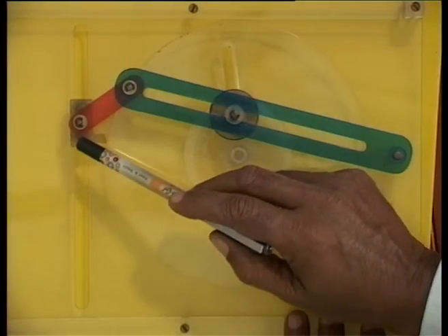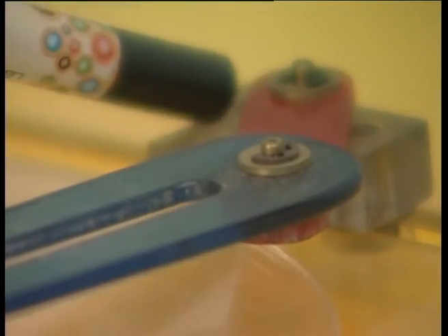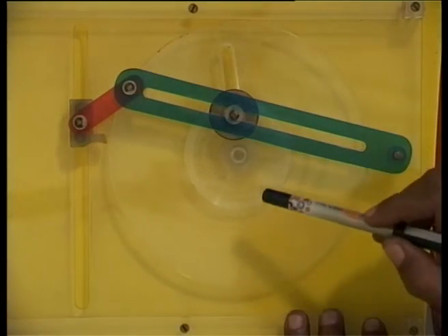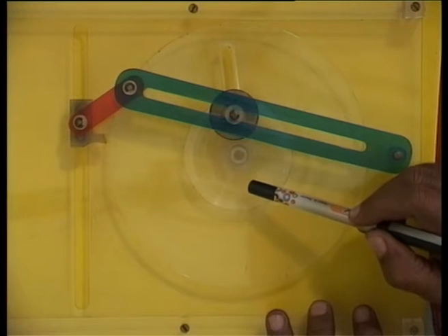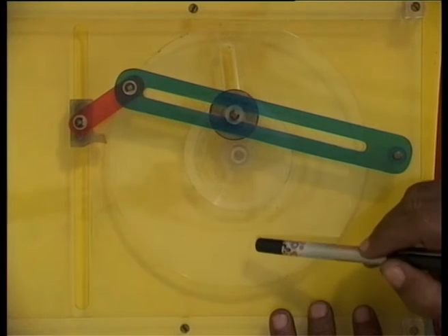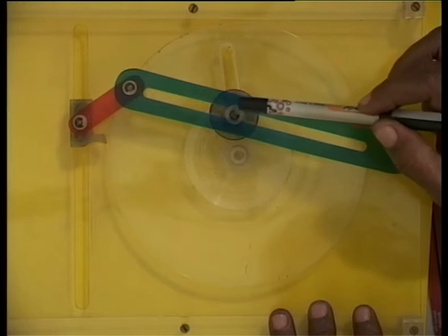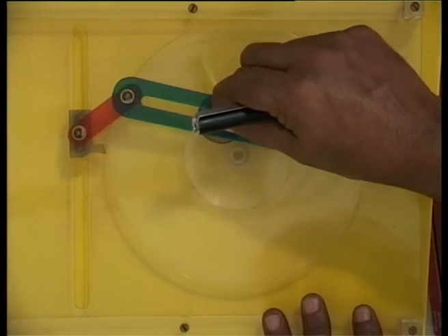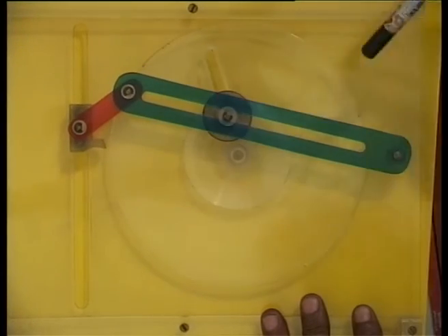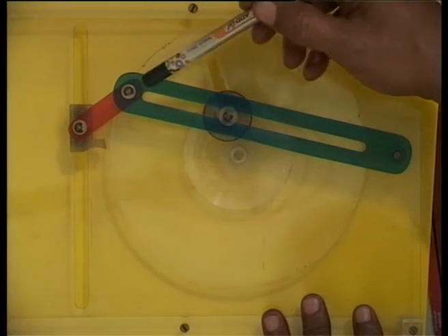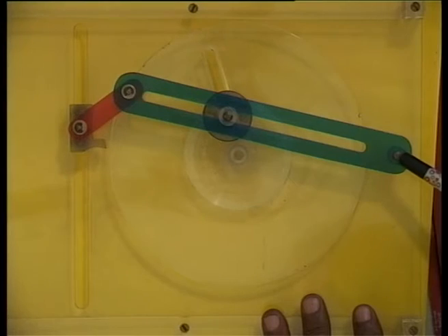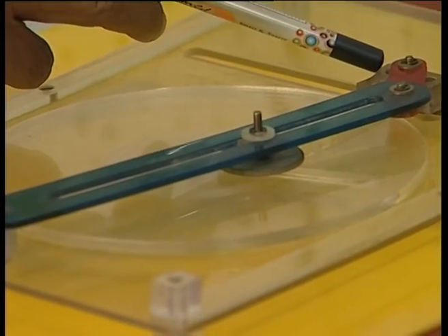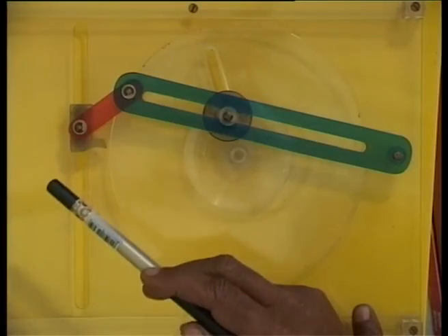This is the cutting tool. This tool holder moves in a slot in the frame of the machine. This is what is called the bull gear, which is rotated at a constant speed. And here is a block which is hinged to the bull gear, and this block moves up and down in this slotted lever. The slotted lever is hinged to the frame at this point, and the slotted lever is connected to the tool holder by an additional link.